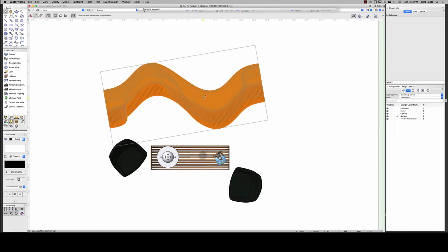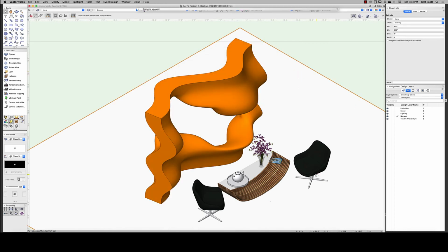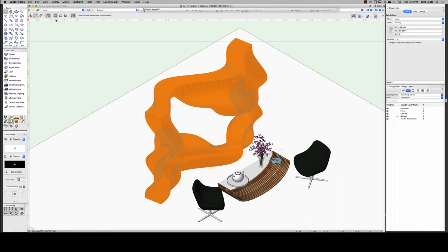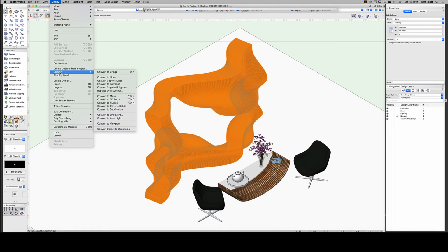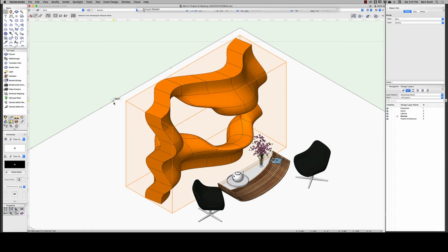So if you select the object and then go to Modify, Convert, and convert it to NURBS, it will think for a minute, and it breaks it up into basically tiles that correspond, or at least seem to correspond, to the original 8x8 subdivisions.